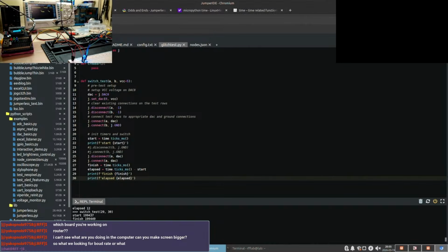So there's actually two of them. There's two dips occurring. And they're lasting, let's see, we can measure it. This is 5 milliseconds, so 10 milliseconds. And then the code says 12. So, I mean, that's kind of on point, right? So let's do, is it fast disconnect, fast connect?